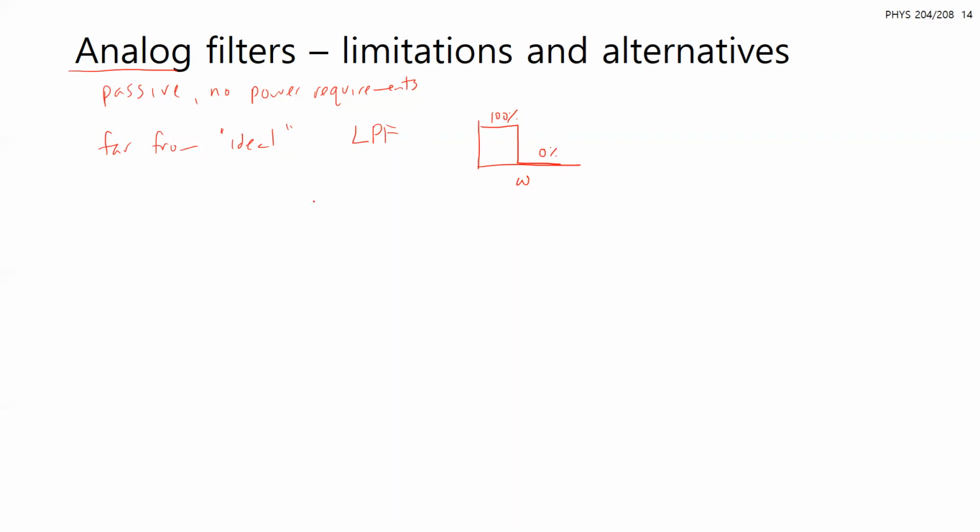And you've actually seen artifacts from this show up in the lab, and I'll upload some notes about this, with the DSO, and I saw a lot of this in your data in the last lab report in lab 2. For a square wave input, you have amplitude versus time here. If you zoomed in, you would actually see some oscillations at the edge of your square wave, because the DSO is actually acting as a low pass filter with a 10 megahertz cutoff.